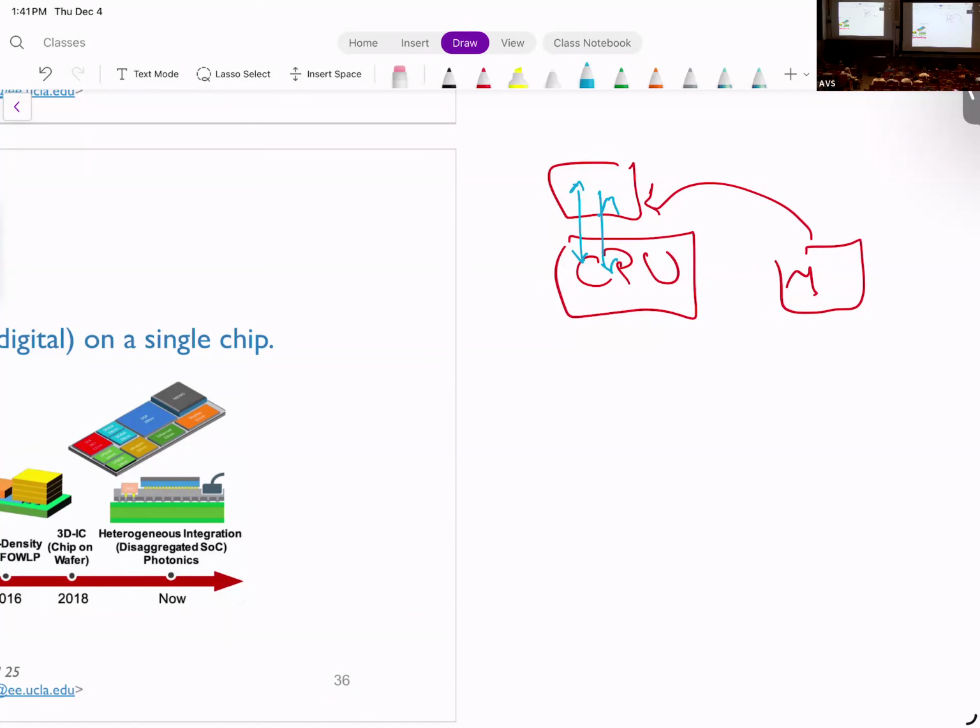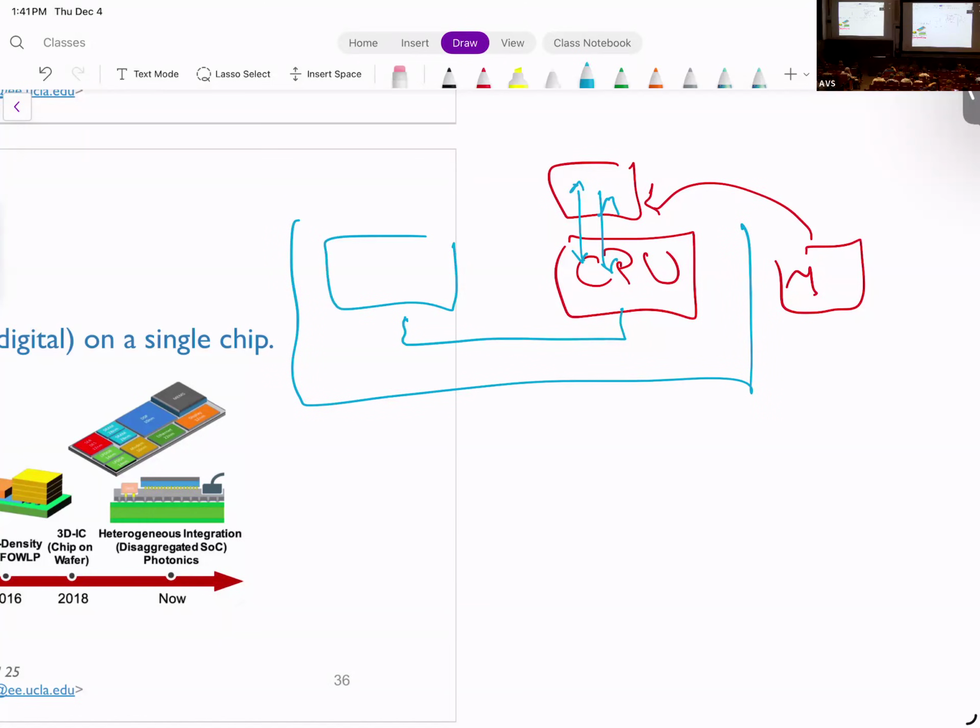So is it simply faster because of physical proximity? Yeah, from the physical and the technology. When you have a PCB, if I have a CPU here and the memory here, I have this thing called a bump. You've probably seen these bumps when you solder. These are really nasty bumps, but in commercial products there are SMDs, so small bumps. Nonetheless, these are a few micrometers. And they have a large capacitance. So talking from this bump to the transistors inside here, it's a lot of capacitance that I need to drive. So the delays are large.